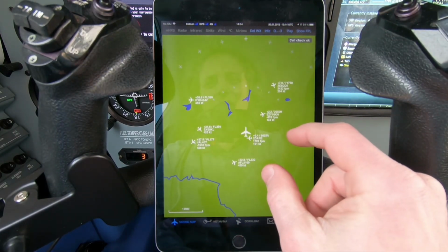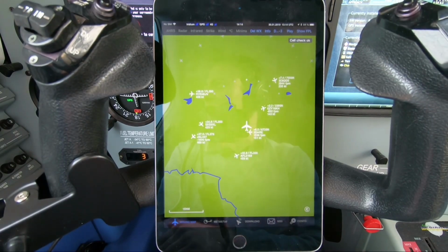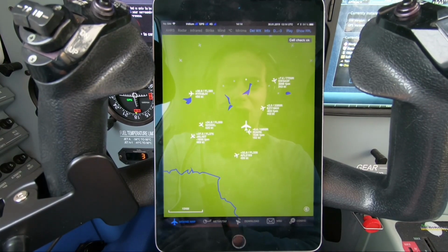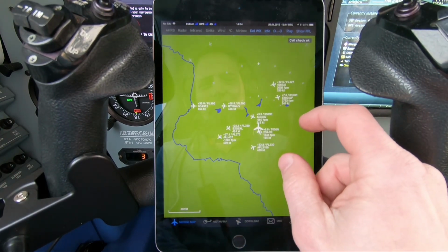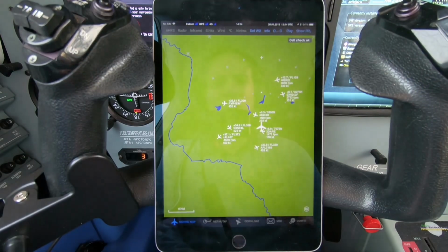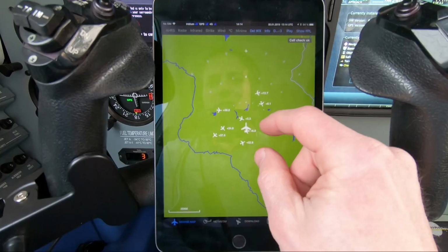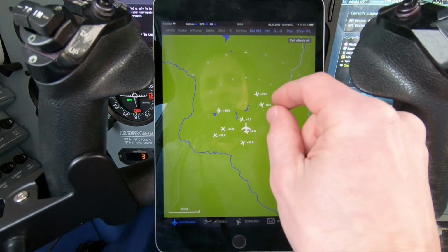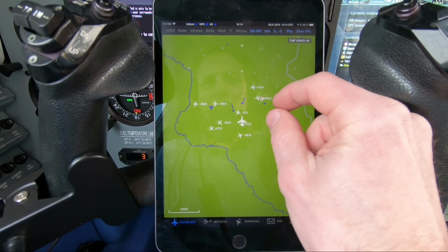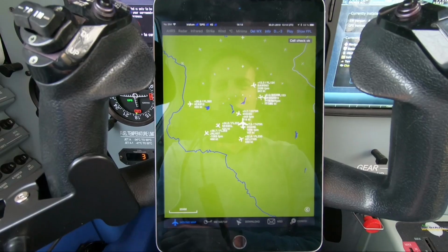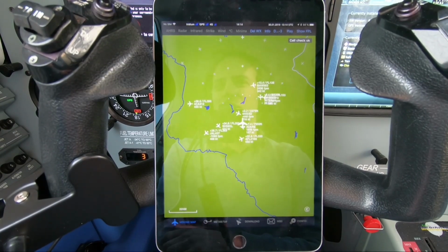Next thing you notice some other aircraft. This is because the ADL200 I'm using and the ADL190 we have on offer have an ADS-B receiver. So you see all the ADS-B traffic around us which is received. On this installation we have approximately a 40 nautical miles range on the maximum signals we receive. If we zoom out, we just see the altitude difference, and if we zoom in, we get more details on the aircraft. This information is received all the time. It's obviously subscription free because it's ADS-B. But as you know, ADS-B weather is not available outside the US. So this is only ADS-B traffic, and the weather is through the Iridium satellite network.